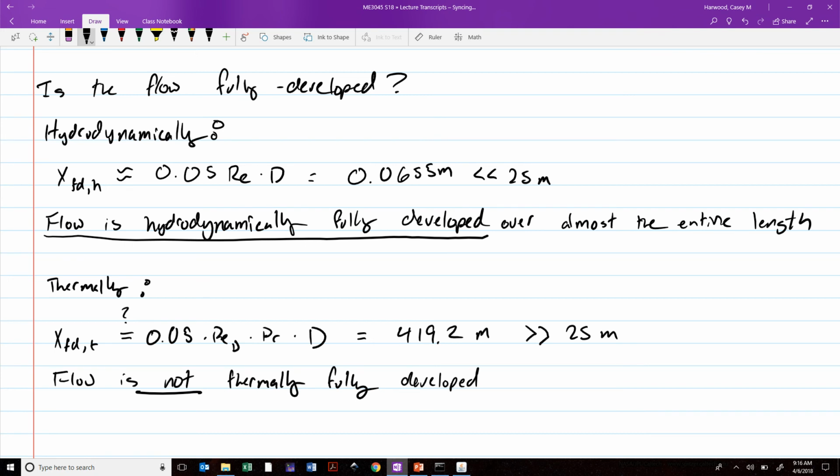This is a very common case. In fact, it'll occur a lot of the time when the Prandtl number is large. It's very uncommon that you'll have a thermally fully developed flow that is not yet hydrodynamically fully developed. So they haven't even bothered giving us a correlation for that case. We have a case for thermal entry or combined entry, which is when it's neither hydrodynamically or thermally fully developed. Anyway, so the one we want here is 857, which has this new variable in there, right?